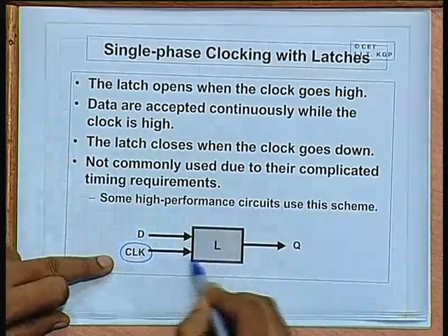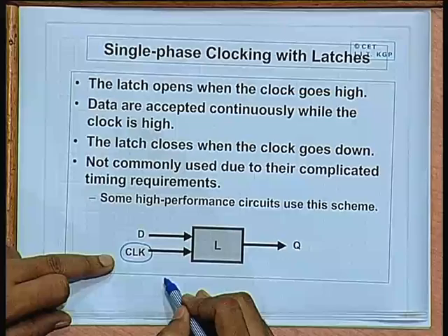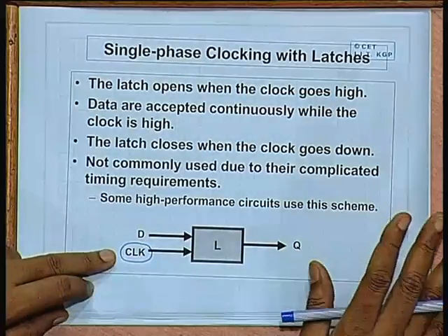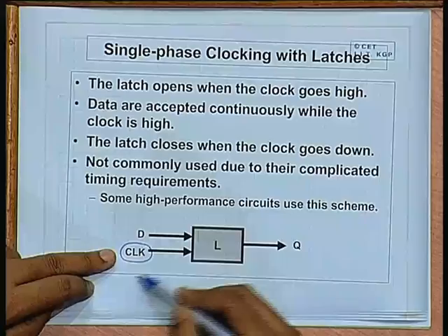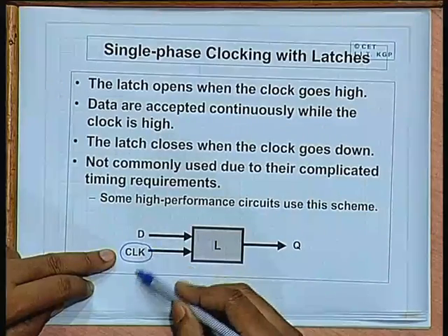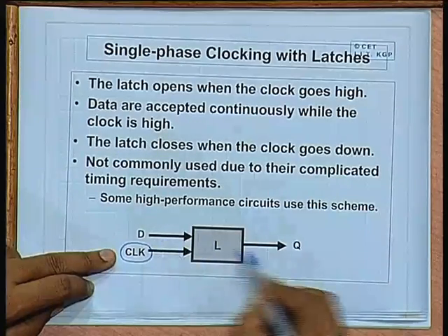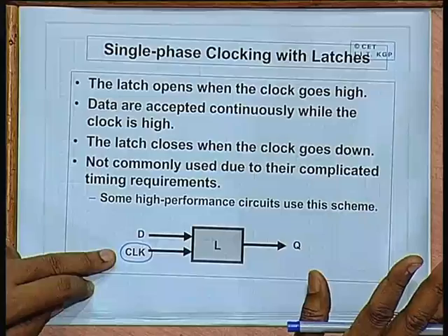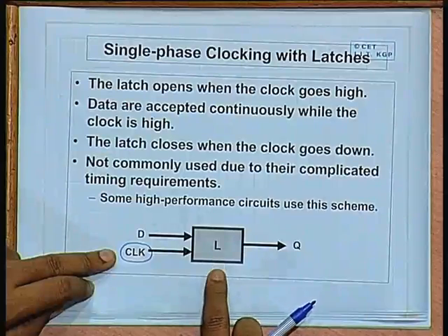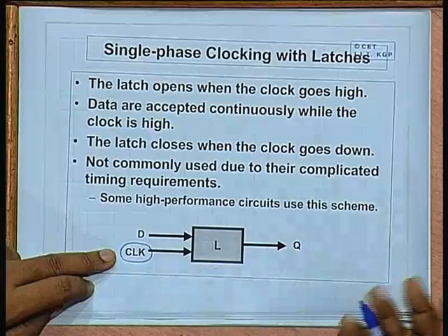Latches are sensitive to level, not to the edges of the clock. Normally, in conventional designs, we do not go for latches like this, we rather go for flip flops where clock edges trigger the data transfer. They are easier to design, but latch based design also has its merits, in particular for very high performance circuits, for very high speed designs where you need some asynchronous sub circuits in the overall design.